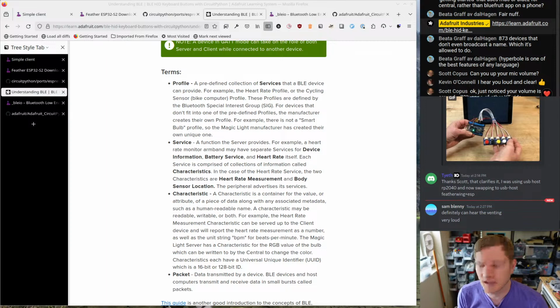So previously in the IDF, you had to know upfront what services you were going to serve before you even allowed connections to come in. But the BLE spec allows you to change the services that you serve dynamically. In IDF 5.1.2, they added the ability to do that on ESP chips, which was a huge blocker for us, because we don't care whether a connection's going or not. We'll just create a service if we want to. We use it for the BLE workflow services. We have two services by default for CircuitPython. One is a file transfer service. One is basically a serial connection service. And then the user can also construct services dynamically from their code to serve.